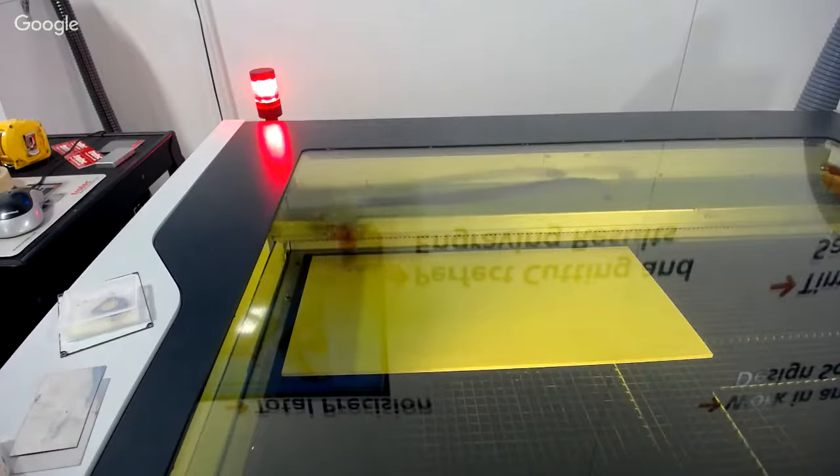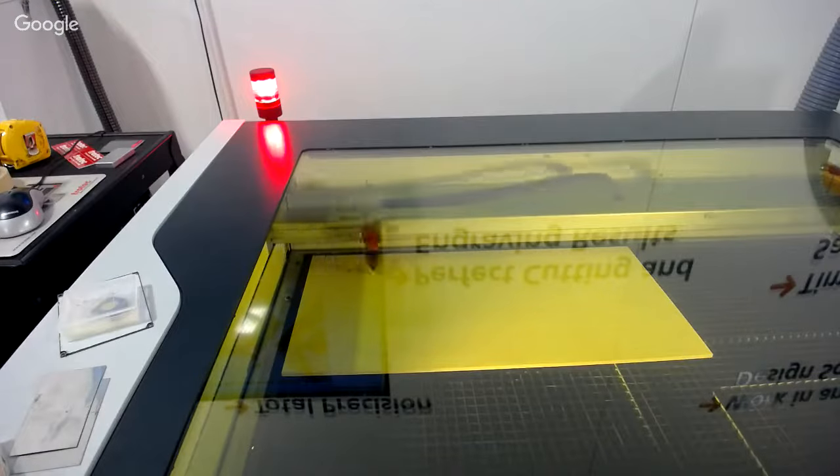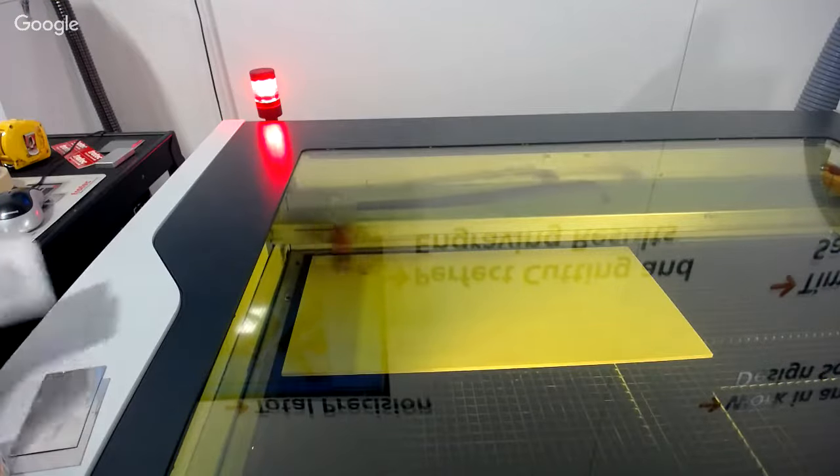And again, acrylic is fine. Glass, again, is similar to the wood settings. So normally when I'm adjusting in wood, I'm using the same adjustment settings for glass. The one thing to remember when you're doing aluminum or glass and acrylic, I'm going to do one after this, is that we need to make sure that we invert the image, because my engraving is going to turn white, not dark. So I need to do a negative of my actual image.